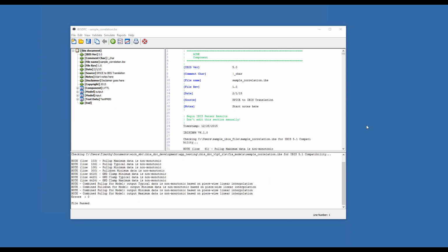And so again, that was really it. That's what I had for today. I hope I didn't go too quick. I hope this made more sense sometimes than just looking at the slides, to understand what problems you run into with IBIS models and what you need to do to fix them, and why you need to go beyond the IBIS parser and do some simulation, and always ask for correlation data. Okay, so that's what I had for today.